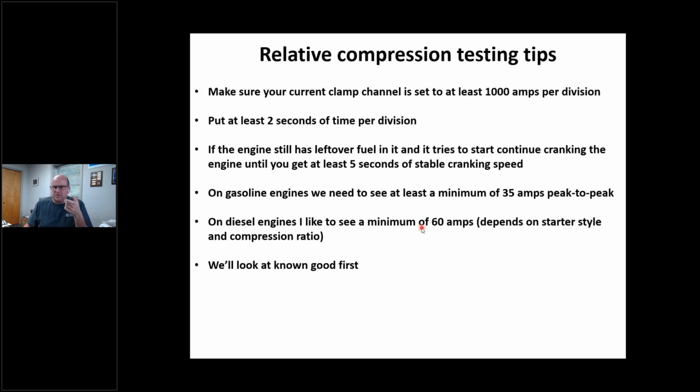On gasoline engines, I like to see 35 amps peak to peak minimum, and I'll talk about that in a second. Diesel engines, I like to see typically 60 amps peak to peak. It depends on starter style, depends what kind of engine I'm working on. But that's typically what I like to see. And let's look at some known good here.